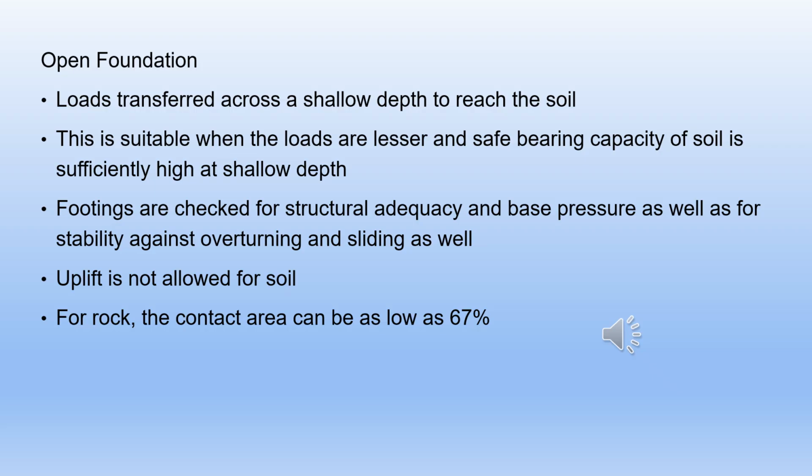First we will discuss the open foundation. It is a type of shallow foundation where the loads from the substructure are transferred to the founding strata at a shallow depth from the existing ground level. This type is adopted when the loads are lesser and the safe bearing capacity of the founding strata is sufficiently high at the shallow depth. The founding strata could either be soil founded below the scour depth or rock.